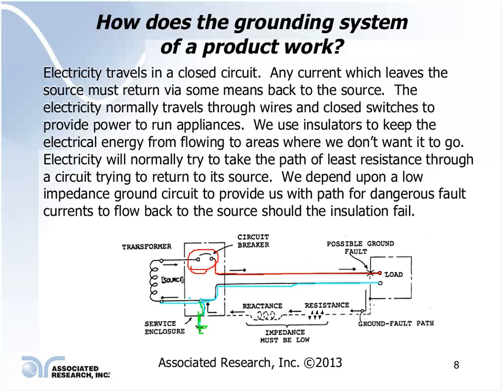There are also fast-acting type fuses and breakers that don't have that type of protection, but they're designed for a slightly different application. But most of the breakers in your home do have some kind of time delay in these type devices.